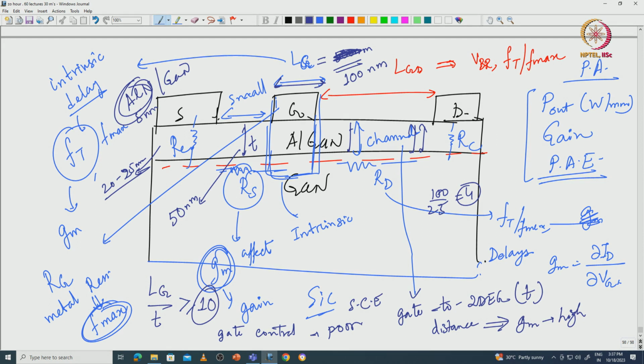sufficiently thin to not do any gate recess and still get an amazing gate control, except that your gate leakage will be high, so you have to try to address that, and your contact resistance is going to be high unless you do a regrowth, and making a regrowth to an AlN GaN HEMT, again this is a process complexity. So eventually everything is a trade off. The process complexity, the cost and the performance have to trade off, otherwise you know that's inevitable.